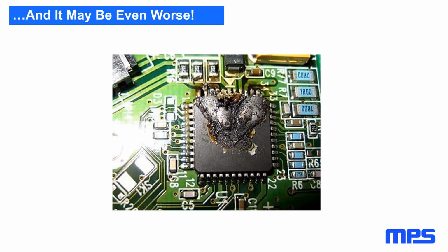There's also a possibility that any given IC might not meet the typical RDS(on) specifications, could be higher, up to the maximum datasheet spec, although that rarely happens. All that, plus your PCB design may not be as good as the JEDEC standard. Luckily, it might also be better than the JEDEC standard. So there's really two things you can do.